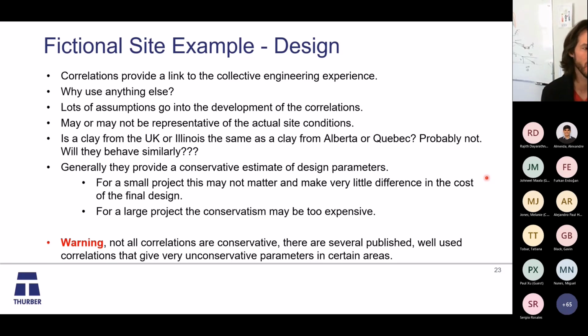There's assumptions that go into that. And you have to ask yourself if they're representative of your actual site conditions. Does a clay from the UK or Illinois behave the same as a clay from Alberta or Quebec? Probably not. But the better question is, will they behave similarly?